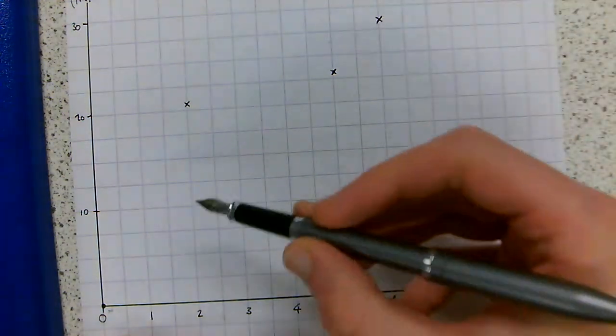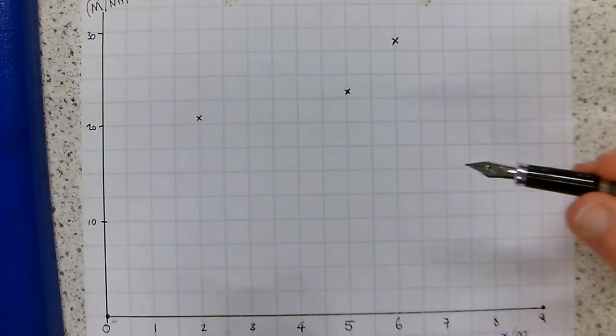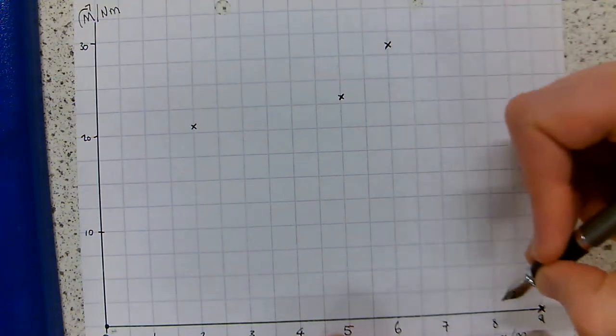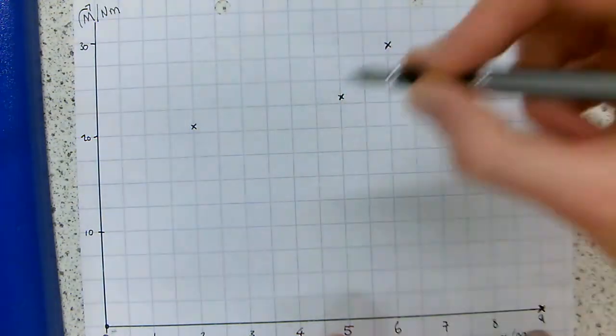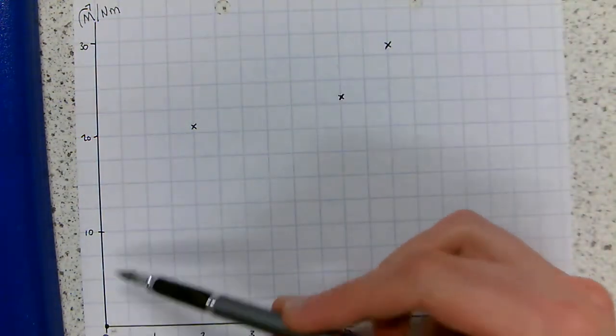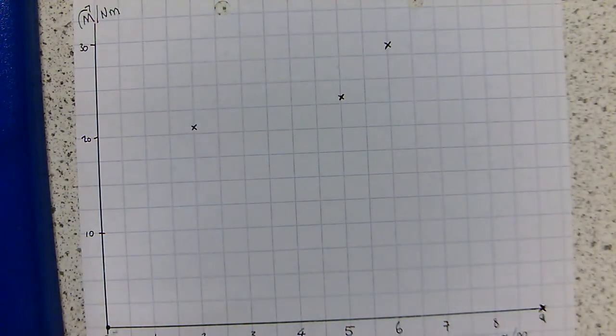Normally in an exam they would give you a piece of graph paper so you can plot these a little bit more accurately. And then we know at the end of our beam it's back down to 0. So then all we do is we join these with straight lines. For point loads you may expect straight lines between our bending moments.